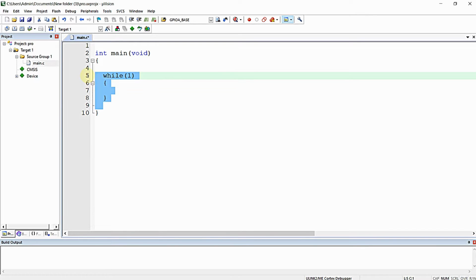So this while(1) is nothing but a never-ending loop, or infinite loop, or super loop, whatever you call it. It will contain the logical part of the program which needs to be executed again and again until the microcontroller is stopped. The portion of the program just before the while(1) inside the main function will contain the configuration lines which need to be executed only once, initially.